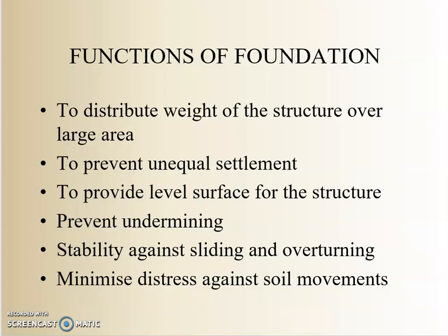Okay, in this particular chapter, the main emphasis will be on settlement criteria. However, that is not the only criteria which decides or determines the size or the type of foundation. There is also shear criteria. Shear criteria we will handle later. Initially, we are only starting with the design or planning of the foundation based on the settlement criteria.